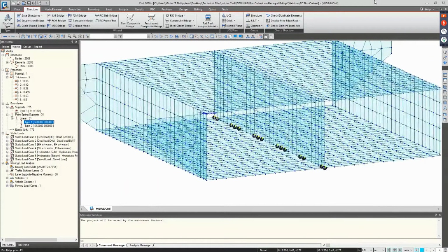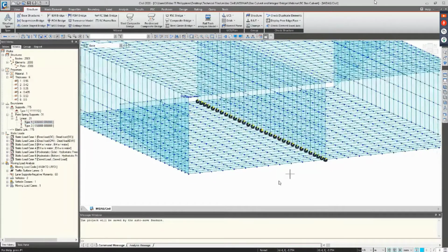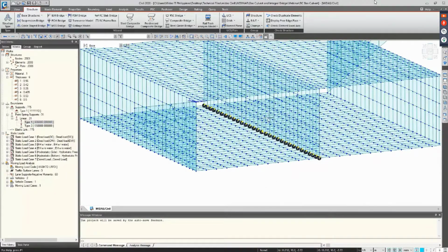The restraints are on the x-axis, and then in the middle, it is restrained in XY, so that it would have a support so that it won't move around inside this structure. So it won't slide longitudinally and transversely. That's why we included the point spring support.